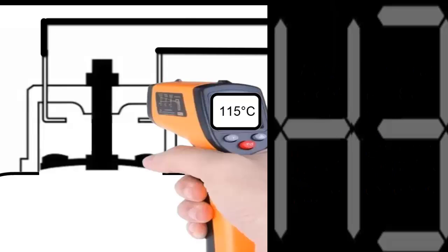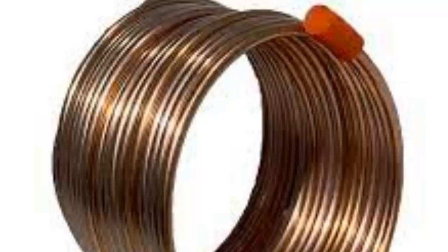8. Review of the capillary tube or expansion valve. Generally, when this component is obstructed, it starts to become excessively cold, sometimes even freezing on the outside.